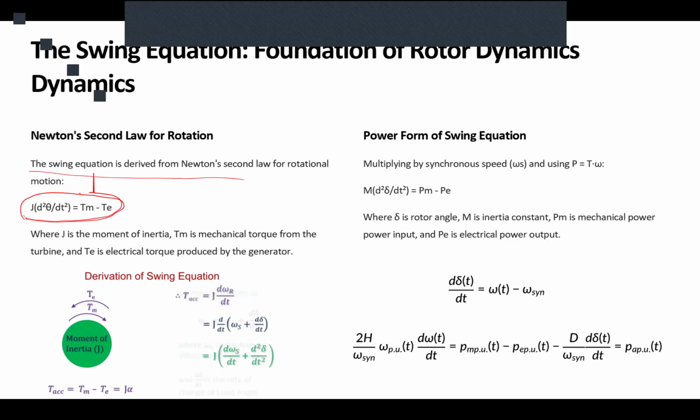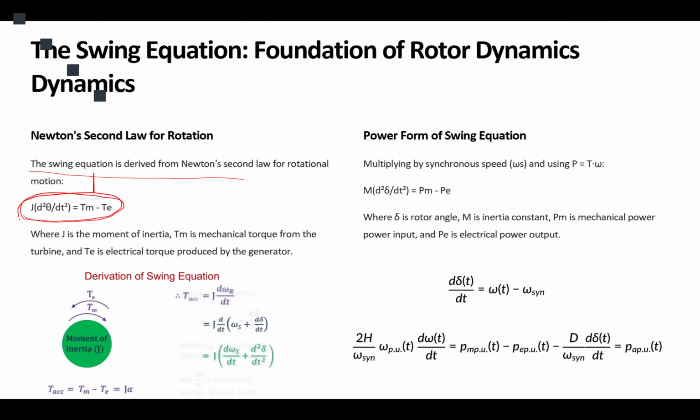would have a second order differential equation that defines the behavior of that theta based on the mechanical torque, electrical torque, and the inertia that the system has.